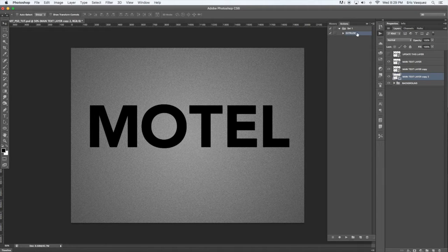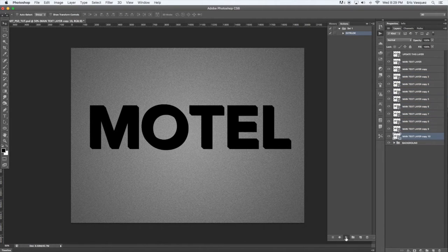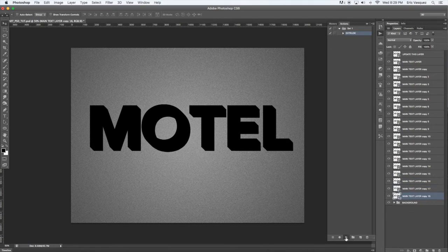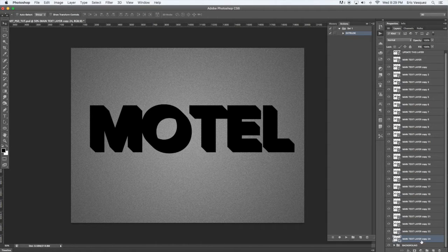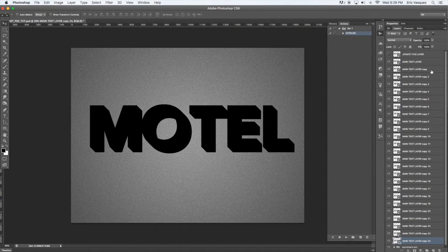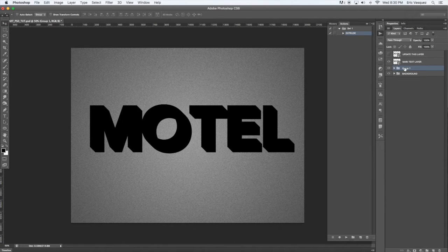Okay, so that's our action. So now if you collapse this folder, you'll have your Extrude action here. And I'm just going to come down here and click the play button. And I'm going to click the play button a lot, all right? I'm going to do it about, let's say, 24 times. And then I'm going to select my bottommost layer, hold down the Shift key, and select main text layer copy. So everything except our main text layer. All right, then I'm going to press Command G to put that into a group folder. I'm going to double click that layer and just call it 3D.